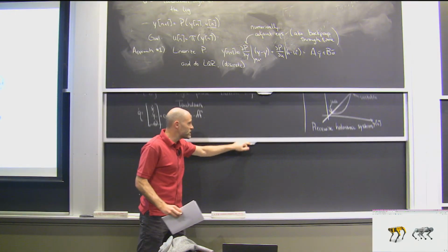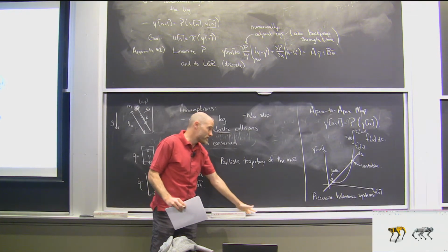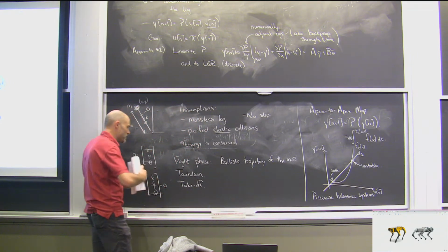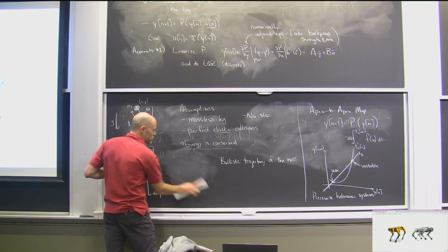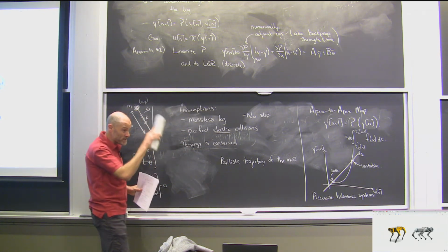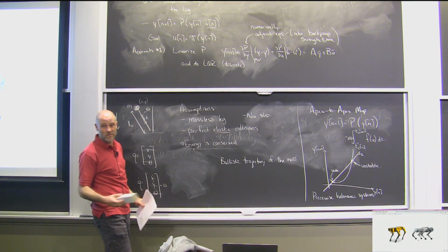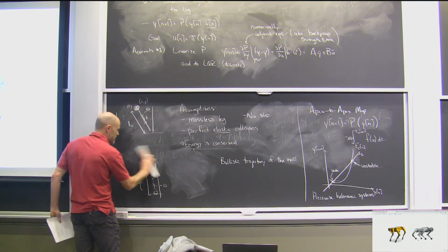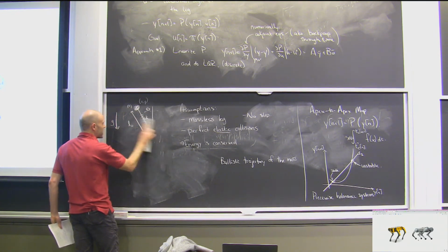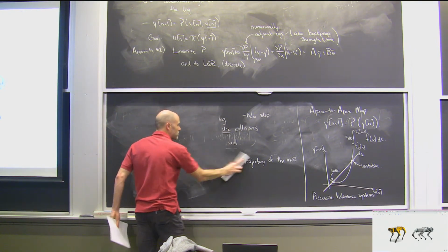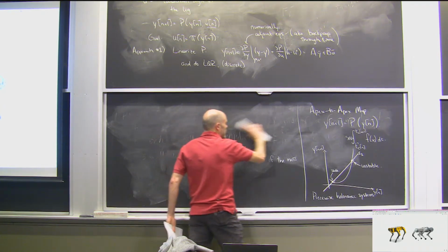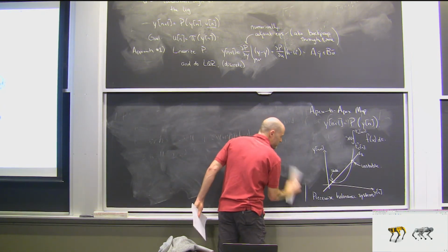To make discrete decisions in a way that's abstracted from time. The duration of that decision is not even set a priori. If I make a different choice for my touchdown angle, I could spend a different amount of time in stance, right? So it's really not any standard discretization of time. It's time abstracted. And LQR can still work on that map.